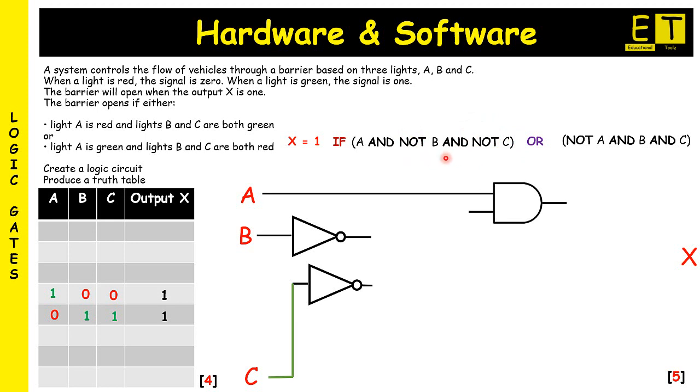And then we need to connect input B and C together with an AND gate and connect that AND gate to the AND gate of A. As you can see here, we have the first set of brackets done. For the next step, you could either do the OR gate, which will output the value X, or you can actually start with the second set of brackets.